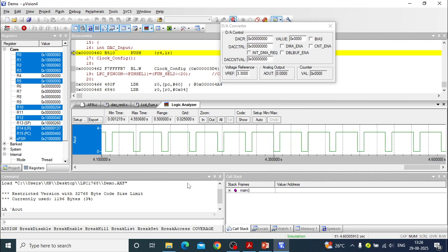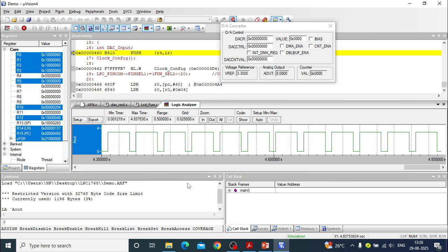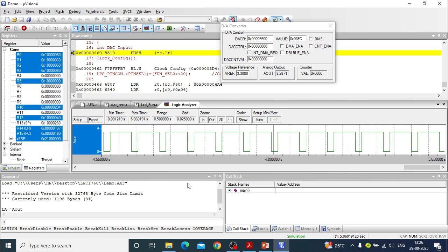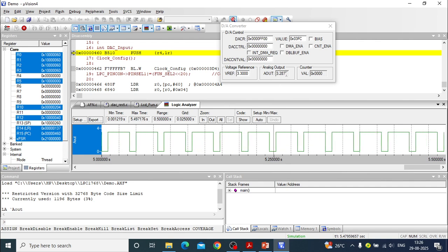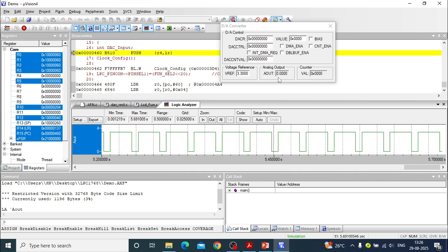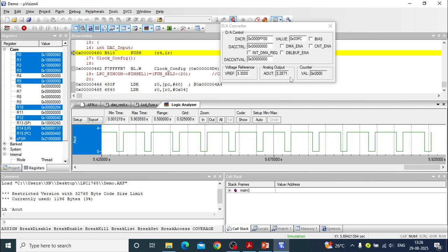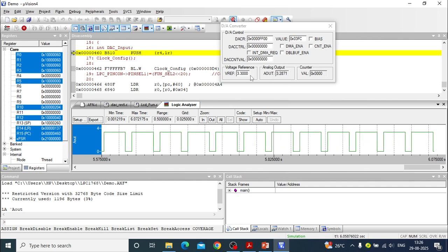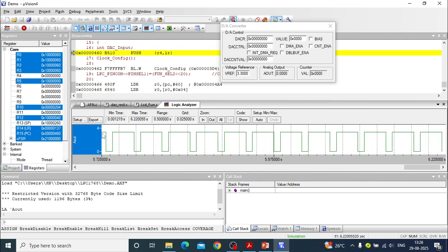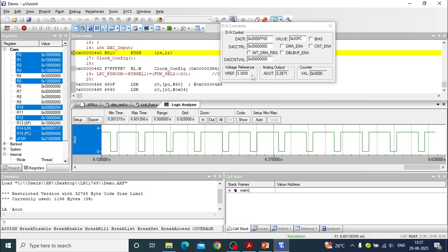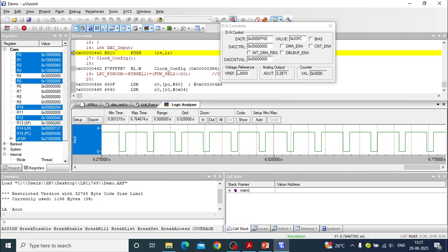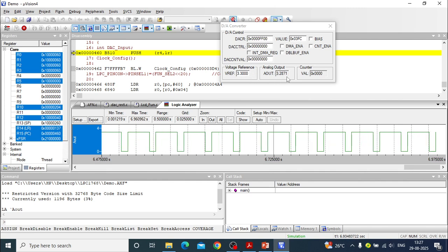In the rectangular wave, output on period will be more and off period will be less. And also you can see here the output analog voltage, it is changing between 0 to 3.28. So this is the reason I told you to take here the 4 as a maximum value. Okay, and the reference voltage is 3.3, so your output should not go beyond the 3.3 volts.